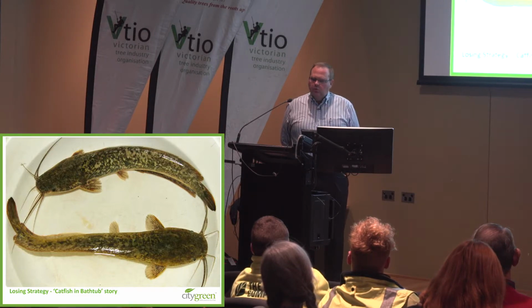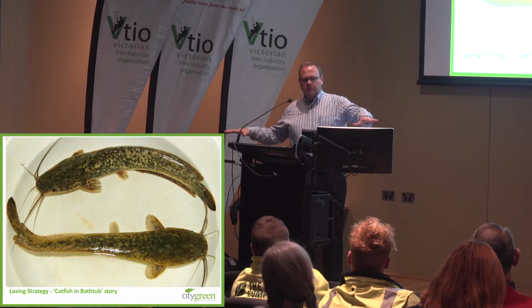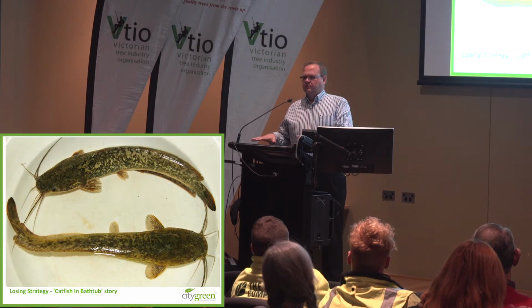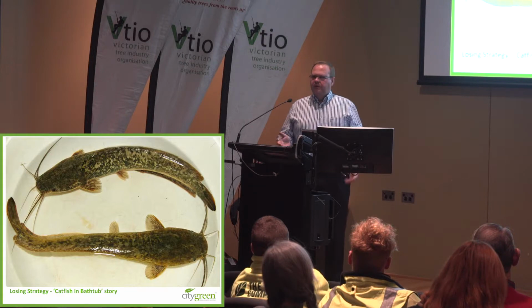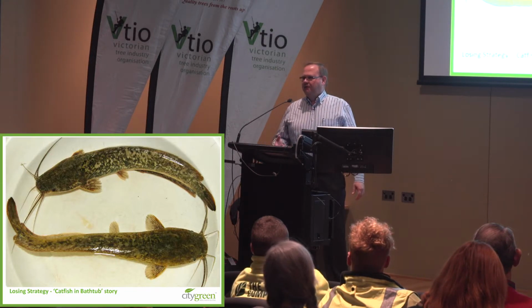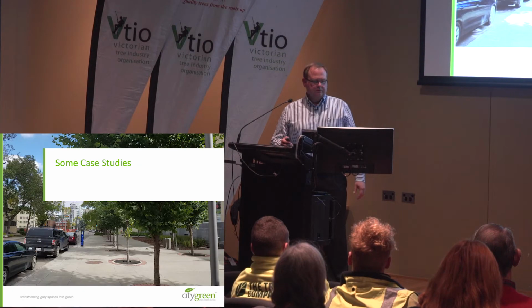And I suggested, well, this loam soil you're putting here under the sidewalk, we could be taking water off the road, putting it through this soil, taking some of those harmful pollutants out of it, and fixing it there rather than it gets into the river system. The thing I love about it, it's not rocket science. It's just realising that this stuff can be done, and it's so simple. But with some of the software that we've got nowadays, we can model it and we can measure it.